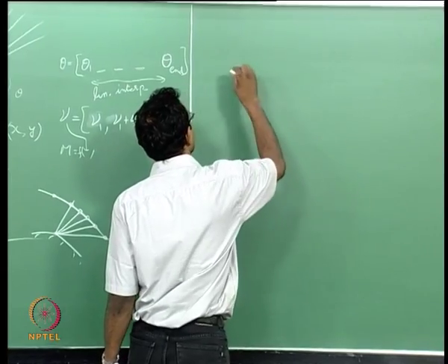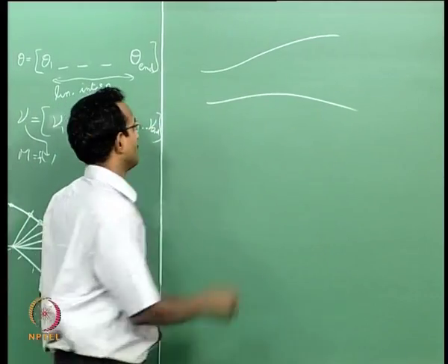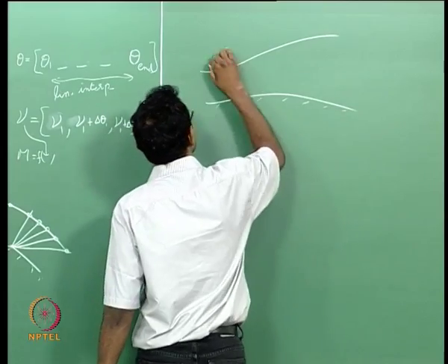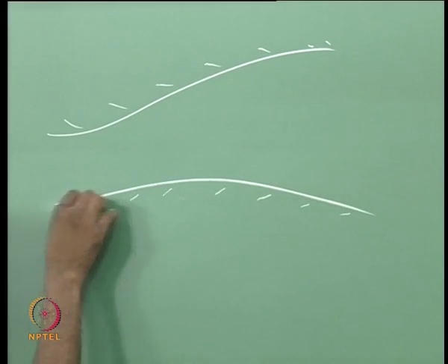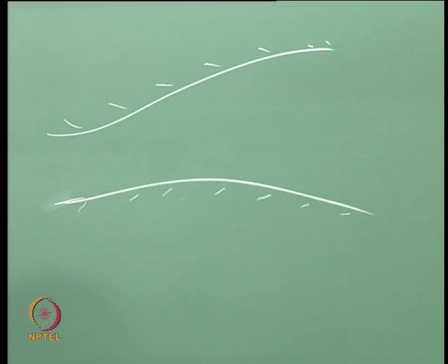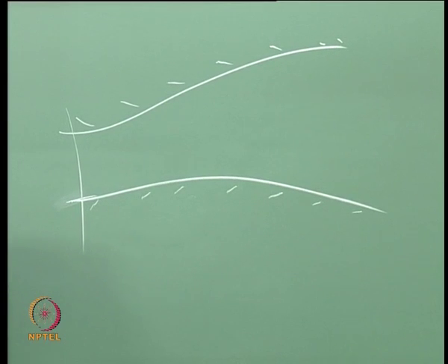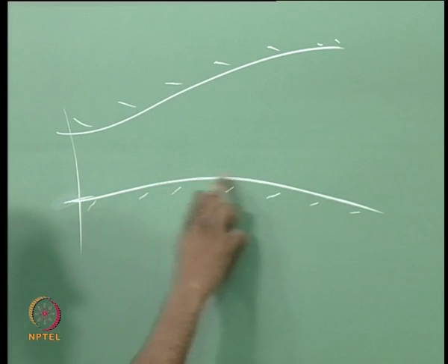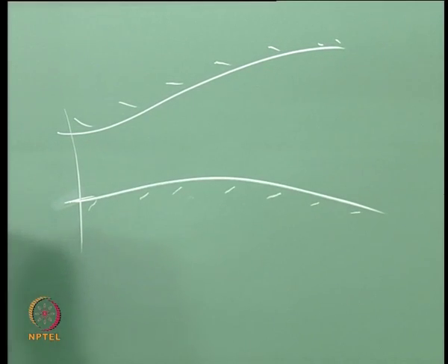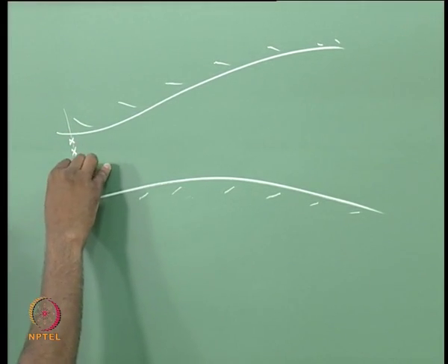But that is the only thing we can solve with the method of characteristics. If I think about how to solve this problem, let us say I want to solve flow through some random duct. So this wall geometry is given to me. I know the exact wall function, the X, Y values of this wall, exactly. If I know that, we need to start somewhere. We know that we always solve towards downstream, which I already talked about once last class. We need to be given upstream conditions so that we can solve the problem. Okay. We are given the wall conditions, the wall boundary. We should also be given the upstream conditions, which let us say somehow I am given these points initially.